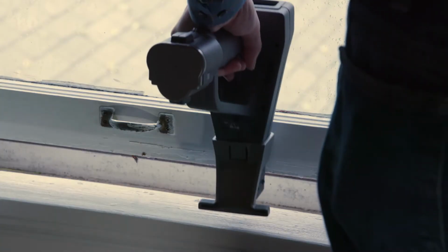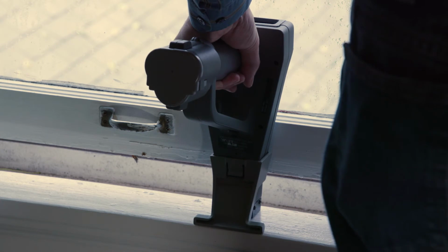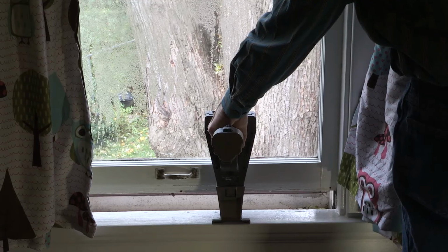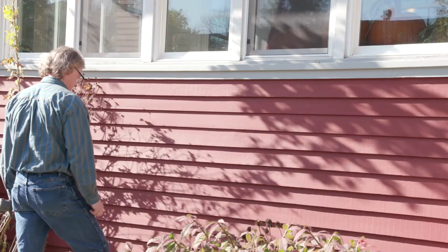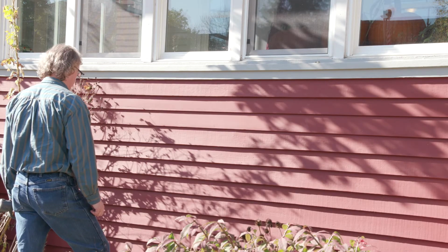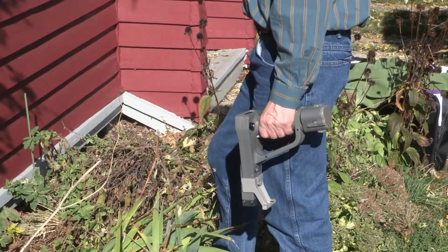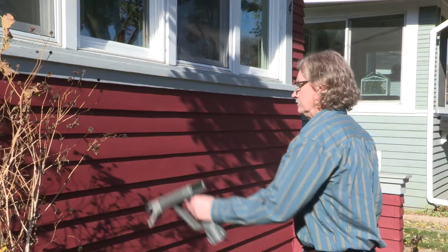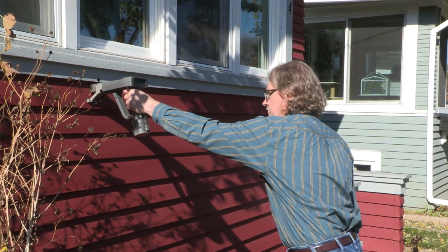Then proceed to take readings on every surface or testing combination in every room equivalent that has deteriorated paint, is a friction or impact surface, or shows signs of chewing. You do not have to test surfaces that are not deteriorated. Take readings on areas where the paint is the thickest, making sure to get all layers to represent the complete paint history. Remember that color is not an accurate predictor of paint history.